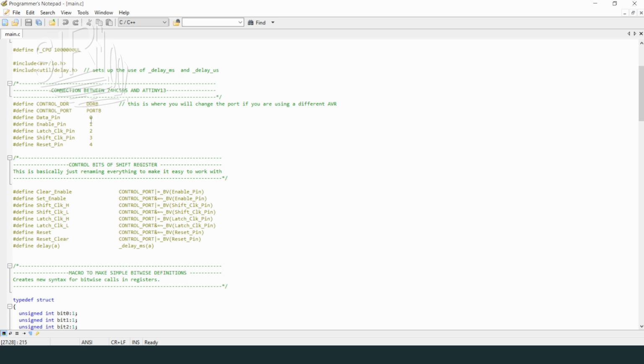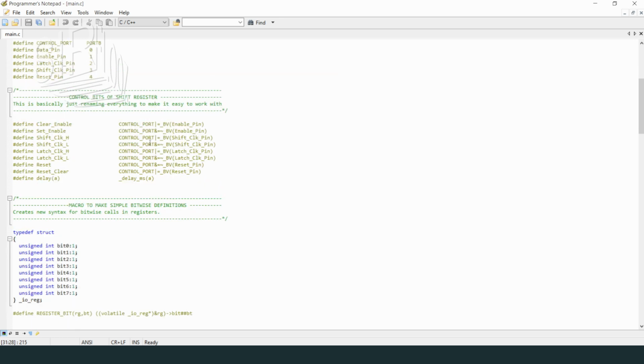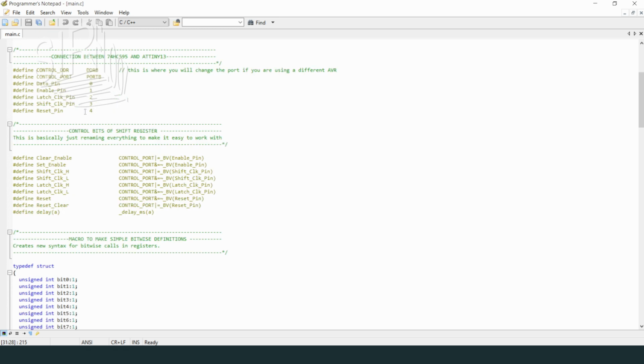So we have 5 control lines. That will mean that all available IOs are blocked on the ATtiny85, but we gain 8 outputs via the shift register, so that's okay. And maybe it's even possible to omit one pin, but I haven't checked that.